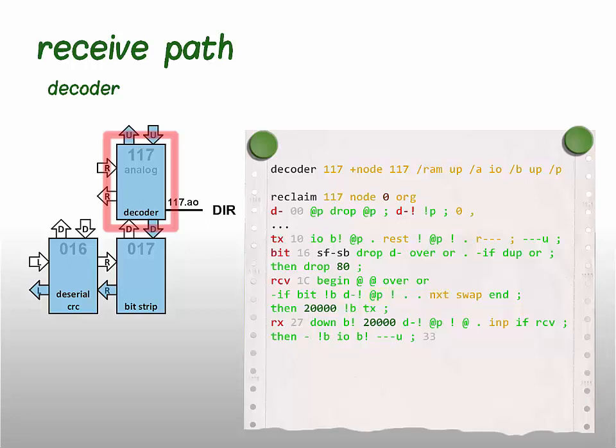Thus we receive and decode all bits until we get end of packet signal, which is reported downstream, and execution continues towards TX, which does some housekeeping and returns control of node 216 to transmit path. Then we jump back to up port. In case there is a timeout reported from node 216, we pass that error to a controller and jump to up port.